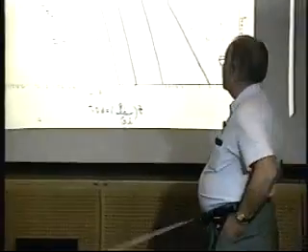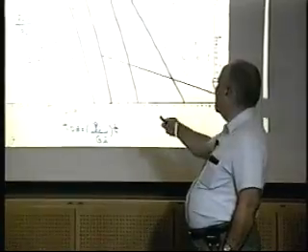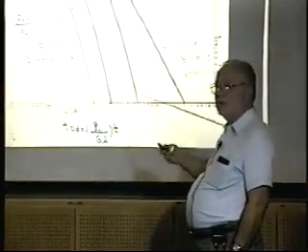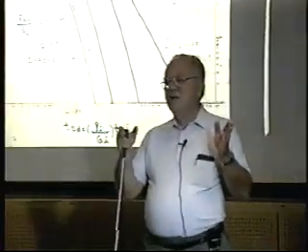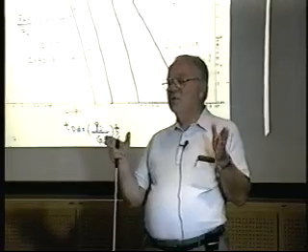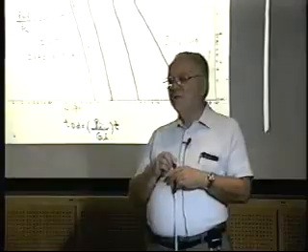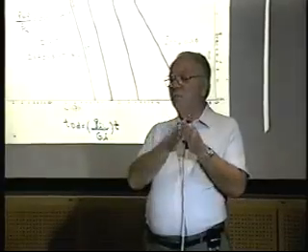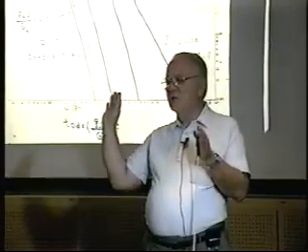The other thing I'd like to point out is you start introducing the concept of the B value reflecting recovery efficiency. Remember, every well starts out at the same location. It doesn't know if it's going to have a water drive or gravity segregation or gravity drainage or anything until the pressure transients hit the boundary. Every well, regardless of what it's going to turn into, starts off at the same place for a given KH and skin.